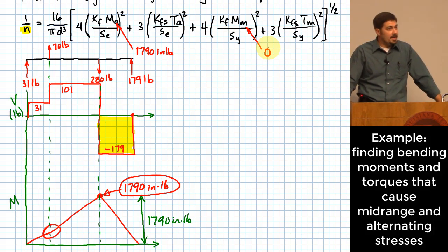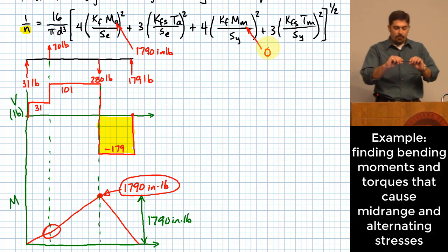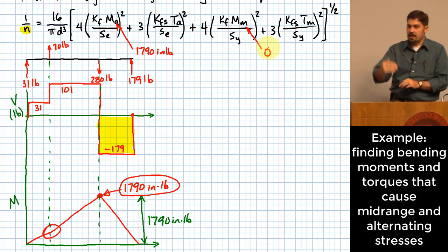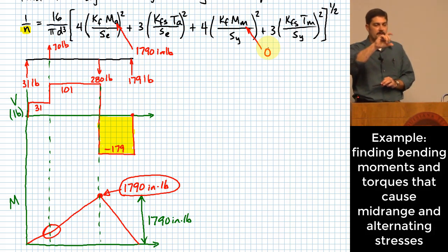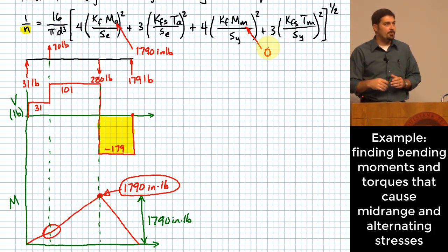The reason why is that flexure that happens in there is going to alternate between negative and positive of the same number, right? It's going to basically go from a negative stress to a positive stress to a negative stress to a positive stress, and it's going to be the same value. Another word for this is fully reversing. Okay, so there's that.